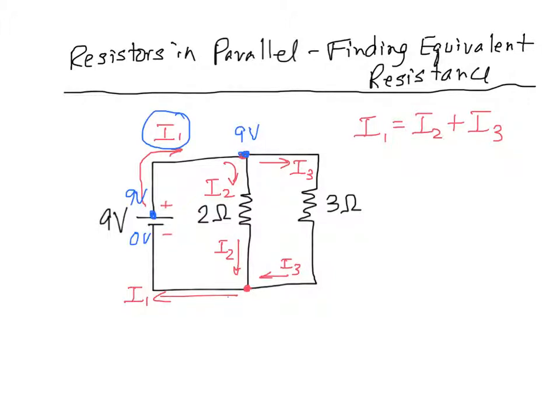Likewise, on the bottom side, if the negative terminal is at 0 volts, so that the change in voltage across the battery is 9 volts, and there are no resistors all along this bottom edge, that means there's no voltage loss across that wire. We assume ideal wires. This junction point would be at 0 volts, as would this one, and this would also be at 9 volts.